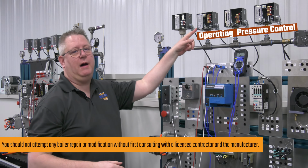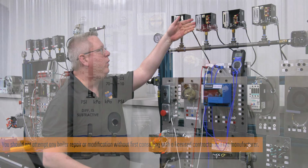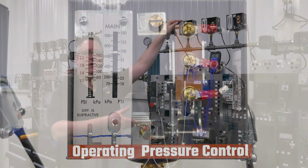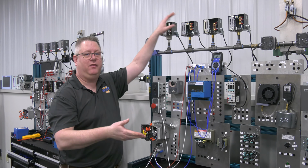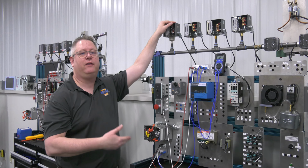We're looking at the operating pressure control. The operating pressure control on a boiler has sort of a name that doesn't match what it does. The operating control name would imply that it's this control's job to tell the boiler when to start and stop, and that's true, but it doesn't tell it where to actually operate at. That's the job of the firing rate control, and we discussed and looked at that last week.